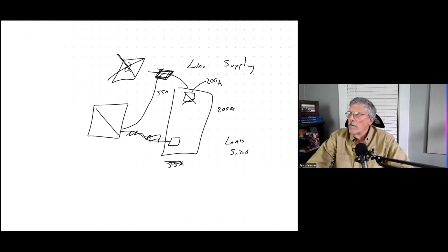And that's fine. We're not affecting the bus bar, which is the thing here that's rated 200 amps, because the power is going to flow here. If I don't need it for my load, it's going to go out there onto the grid. If I need it for my load, it's going to flow out here to the loads. So this is a line side or supply side connection, and this is a load side. And if possible, we want to go with load side.